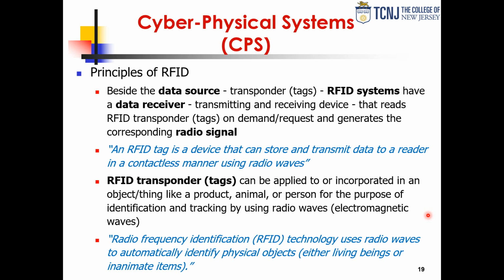It could be a disc, but you have seen your toll tag transponder, so that's one type of casing. But perhaps the most fascinating one is on a label, on a paper label. You can glue it on paper. And then for the metallization for the antenna, you can have paper that is covered by metal and etch away what you don't want, and what you are left with is the antenna that you do want.